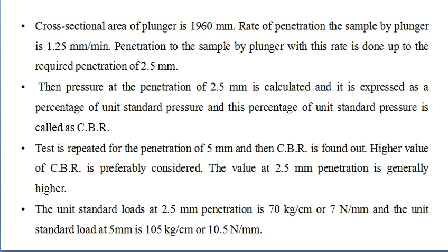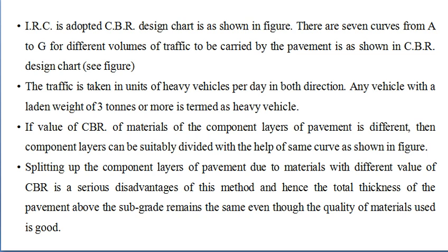The unit standard load at 2.5 mm penetration is 70 kg per cm² or 7 newtons per mm², and the unit standard load at 5 mm is 105 kg per cm² or 10.5 newtons per mm². The Indian Roads Congress has adopted the CBR design chart, which is shown in the figure in the next slide.